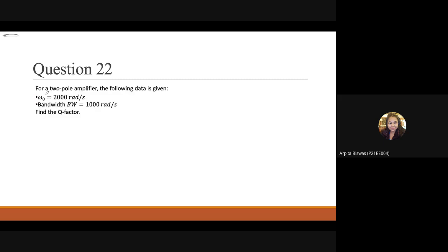This is question number 22. For a two-pole amplifier, the following data is given. Omega 0 is 200 rad per second and bandwidth is 1000 rad per second. So find out the Q factor. Ma'am, 2, ma'am. Okay, Jen, how to find out this Q factor?